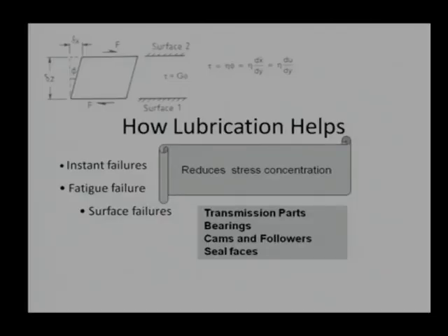In the corrosion case, it will reduce friction as well as wear, but not necessarily come to zero. However, if we provide proper lubrication, the adhesive wear mechanism will come down to zero. Only the abrasive wear mechanism will work if there is no complete separation between solids. If there is a complete separation, or the lubricant is able to provide thick lubrication completely separating the two surfaces, then in that case wear will be zero. That is required for most applications.